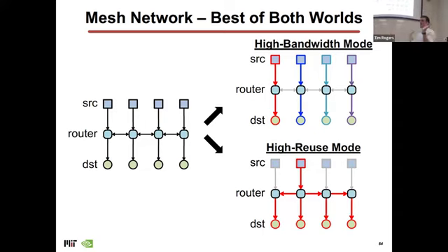And then Bill Dally came along and said, this is stupid, right? Like, why am I doing this? I'm handcuffing myself to this particular configuration. Let's just make the thing programmable essentially by having routers, and then just have packets flow the information through those routers. And then I can have a very flexible topology based on routing packets instead of routing the wires, right? So now the thing that you used to do statically in the VLSI world, don't do that anymore. Just give me a simple static design that I can then program.